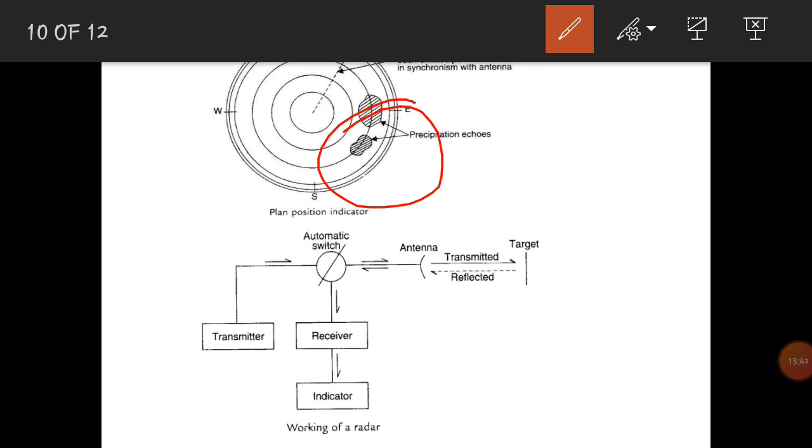Today we find that data are underutilized, and both confusion and misunderstanding exist about the inherent ability of radar to measure rainfall, about factors that contribute to errors, and about the importance of careful calibration and signal processing. Areal and point rainfall estimates are often in error by a factor of 2 or more.